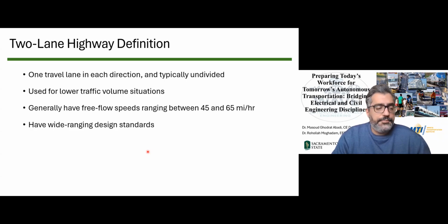What does that mean? If you are driving on a freeway, you should never see a sign that tells you to lower your speed because you're approaching a curve on the roadway. We have to design that curve in a way that it will accommodate the design speed that was true for the entire facility. You're driving 65 miles per hour on I-5. We must design our curves such that it will accommodate that speed.